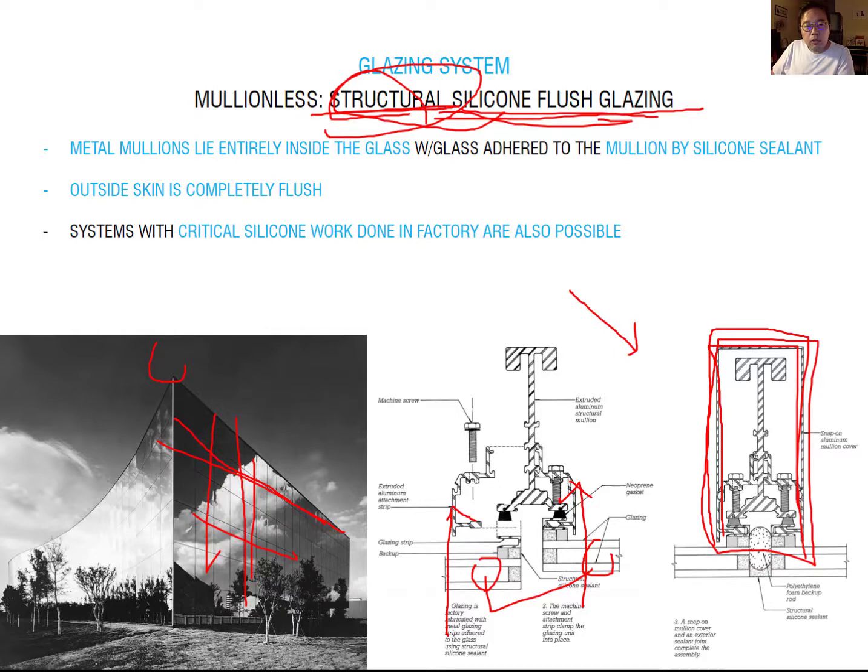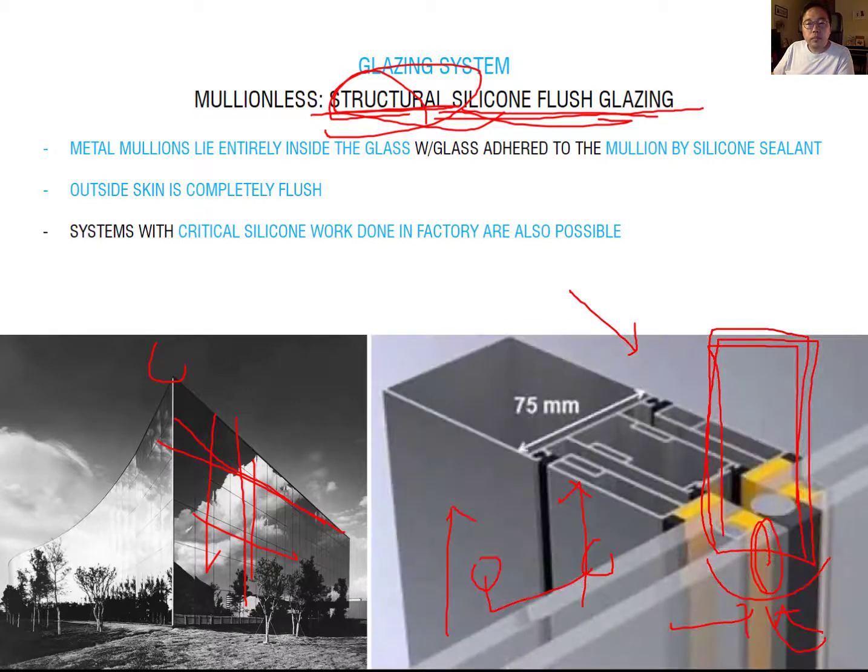So you can just consider using a structural silicone here. This is a structural silicone, and it holds these two glazings tightly. Also, it protects against water and air very well. You can just merge the image here. This is an internal mullion system, and then you can see the more continuous, profiled exterior glazing. So that's why with this vertical or horizontal line, you only see the structural sealant from here.